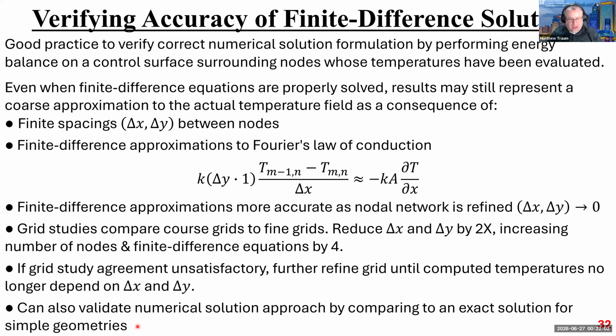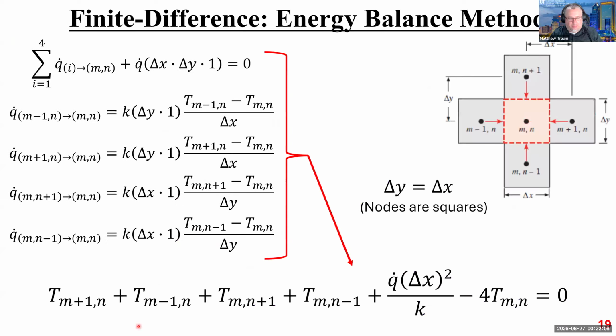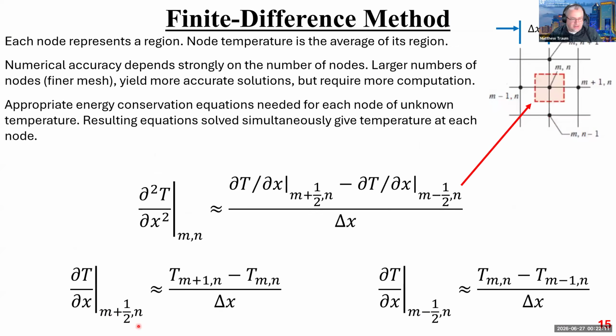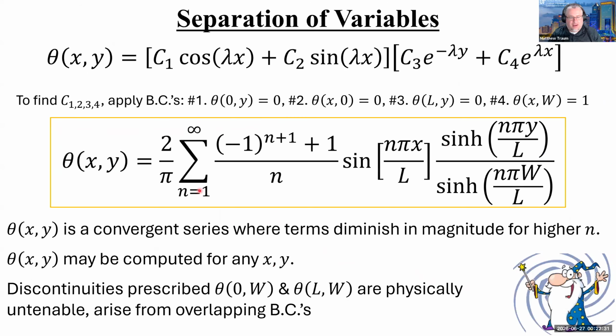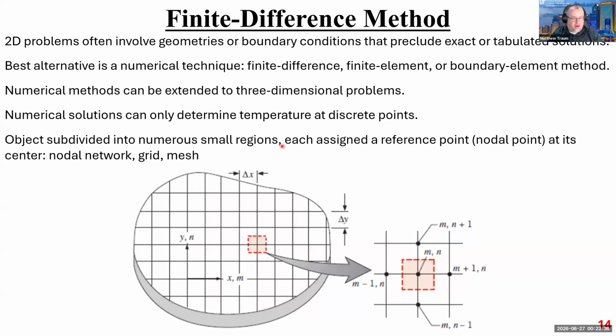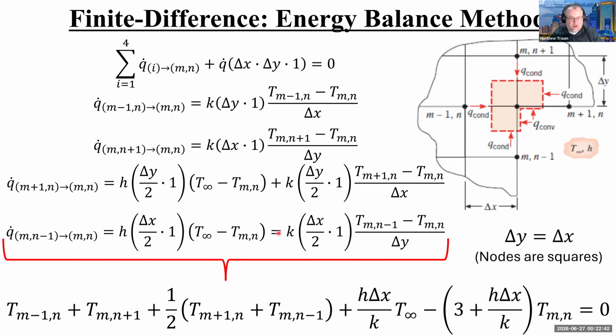simple geometries, right? So if you've got some crazy potato shaped nonsense like this, you could approximate it as a square plate, or find a square plate in there, where you actually know what the boundary conditions are. And then you can use my favorite, the exact solution, to make sure that your computational approach is giving you the correct answer, right? So always good to check the computer.